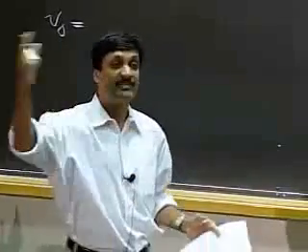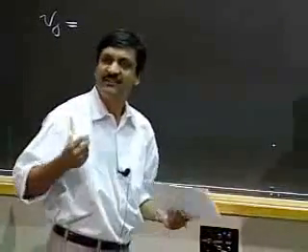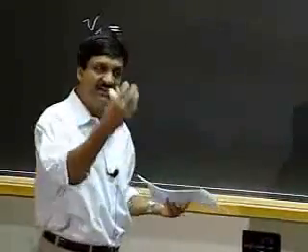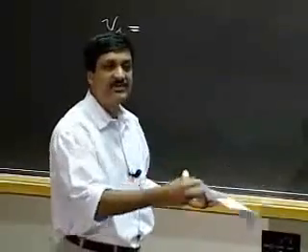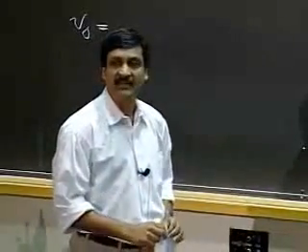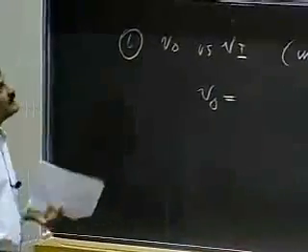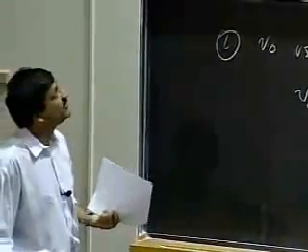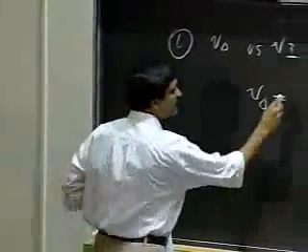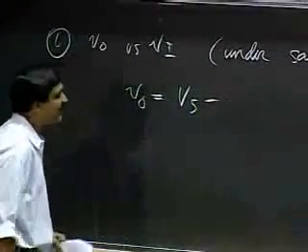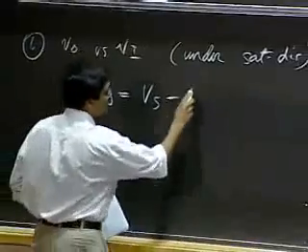And in that data sheet, you see a bunch of curves. So very often, devices come with data sheets. And when you have a data sheet but no equation, then you can apply the graphical method and solve your circuits. Okay, so in this example, assuming I can apply the analytical method, here was the expression that I had derived for you in the last lecture.